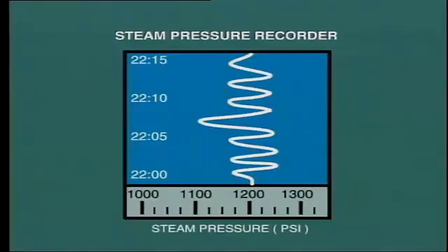And even then, some more delay is experienced in mechanically changing the airflow and fuel supply. Yet further delay is encountered before the increased combustion brings about the desired rise in pressure. The cumulative delay from this control system results in a fluctuating steam pressure.